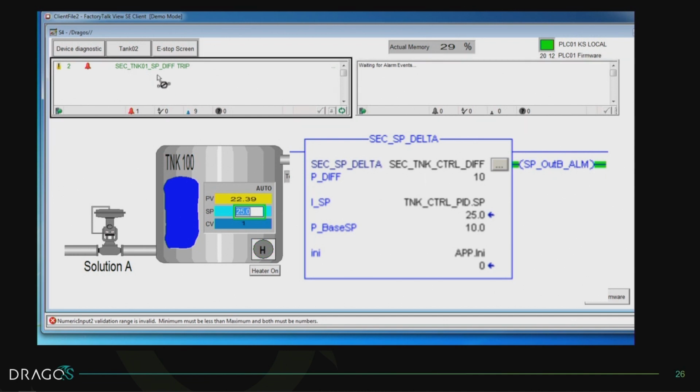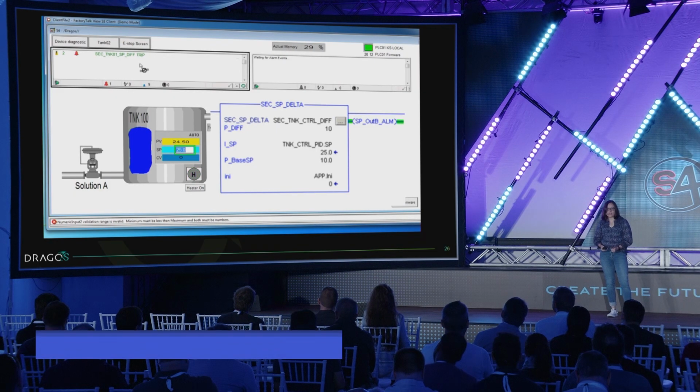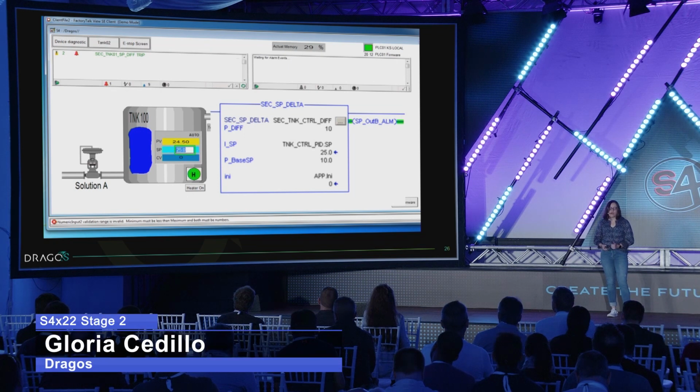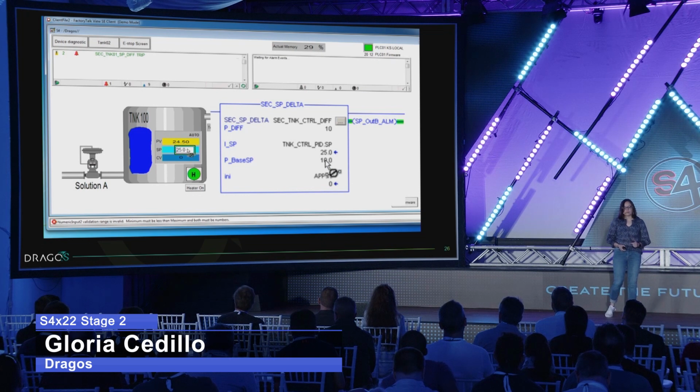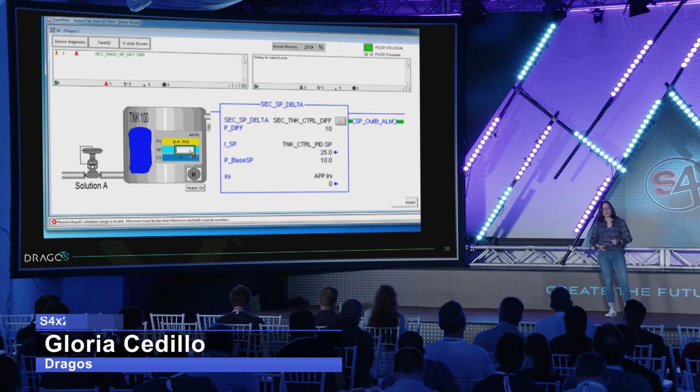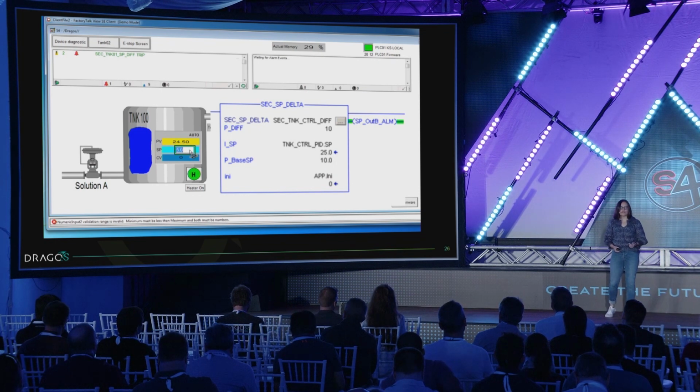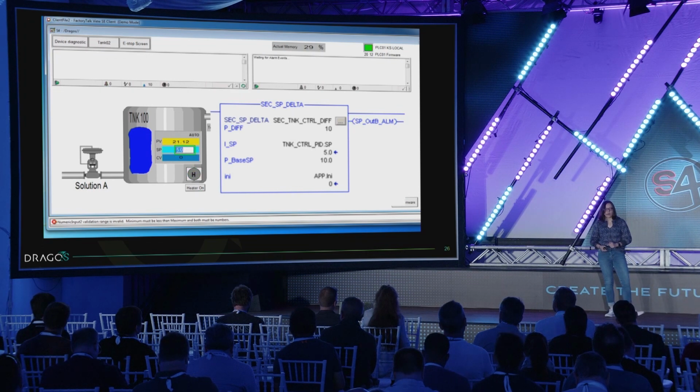And that means that because normally you work in certain range, but you need to have also another range because normally the operations can work in another. There are two ways that you can get rid of that alarm. One is going back to your range that you should be working, or the other one is that you have an acknowledge in another screen that will change the set point base. In the use case that I showed you before, they don't have, that selector is inside of the block, so you don't have to be acknowledging that.